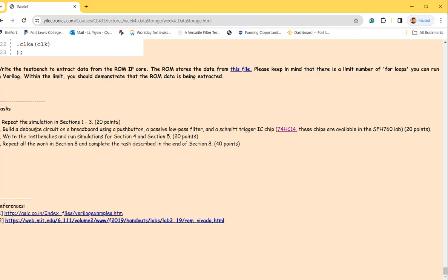You have to use a joystick to control the movement of the character in a game, and you have to engage that push button to the game as well. So when you push it, you can definitely use a debounce circuit in Verilog. But I'm just trying to let you guys try hardware debounce, so it can reduce the amount of code you have to put into your either Verilog, or in the future, if you use the microcontroller, it could be the C code. You don't have to use the debounce to take the space in the loop.